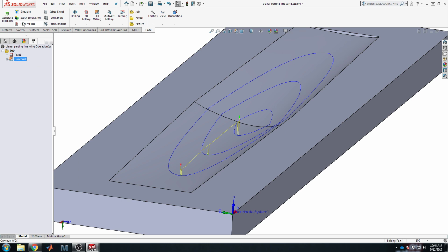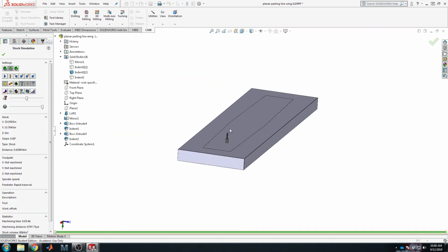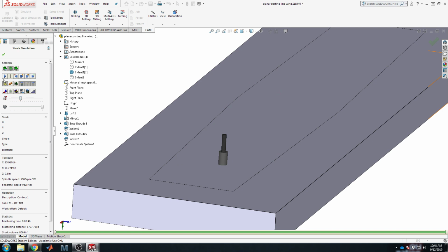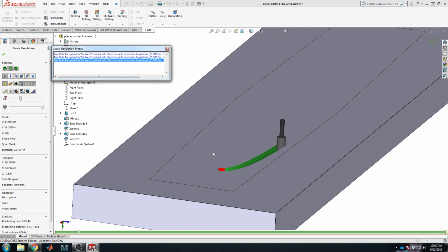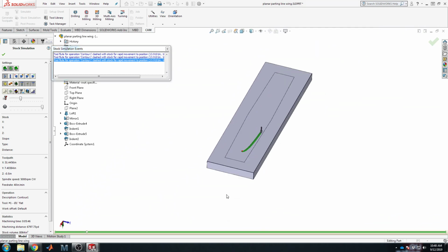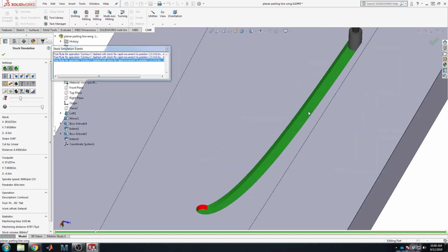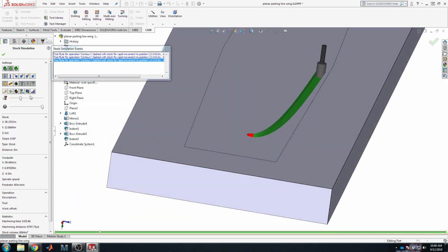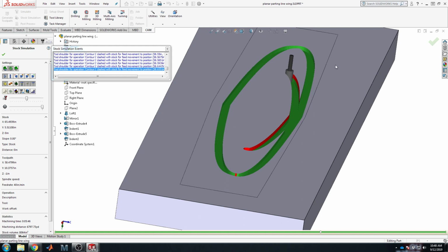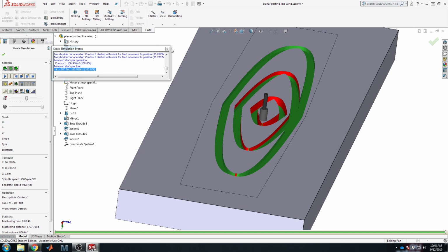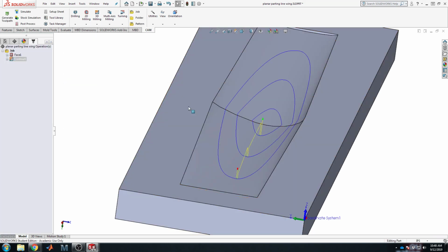So if I select that contour path and I say stock simulation, this actually shows the material before it's cut, and you can slow the speed down a bit and press play. It will alert you with red indication here and warnings here. Anytime the tool really gets loaded up, it threw a warning there because it plunged into the material pretty heavily. This is a full width cut. Let's speed it up a little bit so you can actually see why I don't like this tool path. You can see from the little blue path that showed us before that not only are we cutting too deep, it's not actually cutting out the whole shape. Yeah, this would be bad. If we ran this code, the machine would be more than unhappy. We'd probably break a bit, if not break the machine.